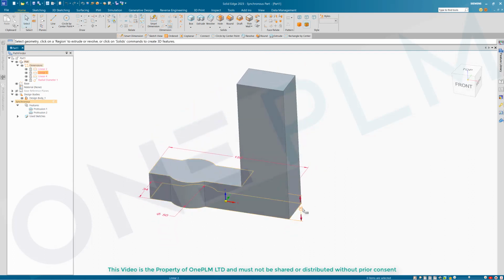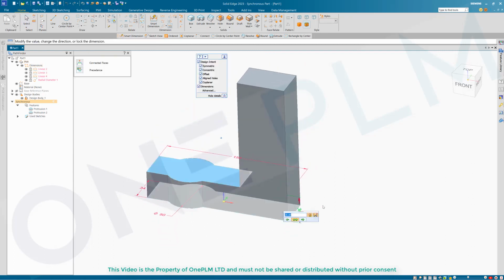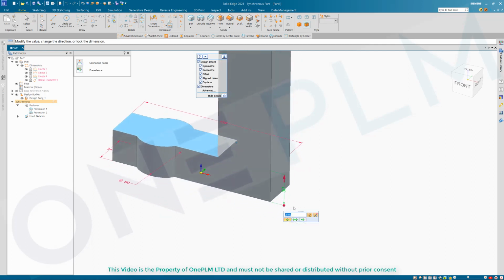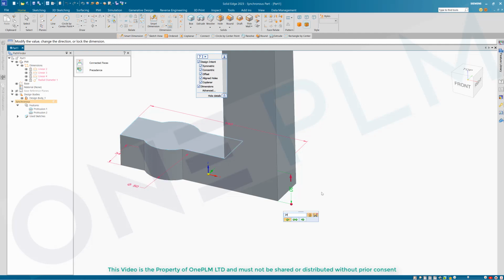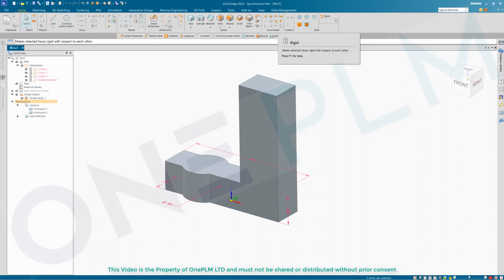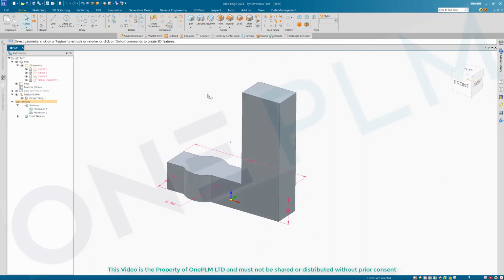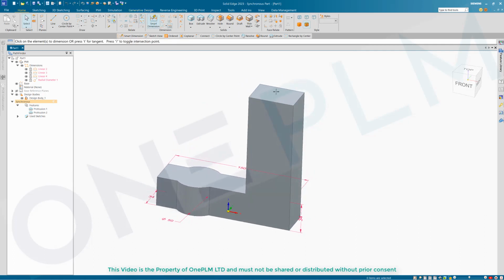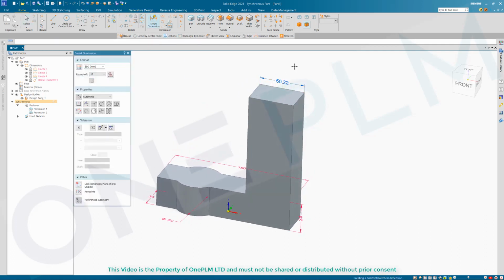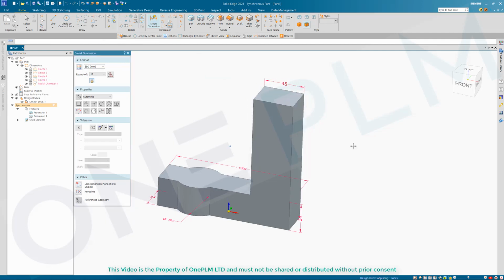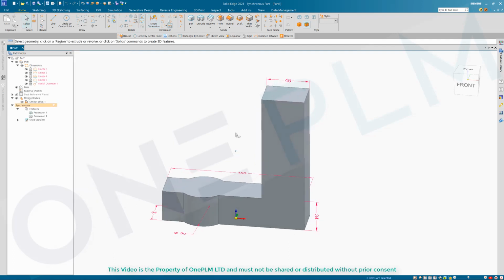If we do make any changes, we can click on the dimensions directly and choose the face that I want to move. Do I want to move the bottom face or do I want to move the top face? You can see our arrow changing on here, and we can use that to make the appropriate change that we need. We have other face relate options that allow us to lock ground faces, ground features, etc. as well, which can be really useful. If we don't have a dimension, we can easily create one, choose the locked option, and then add the appropriate size that we want on there.